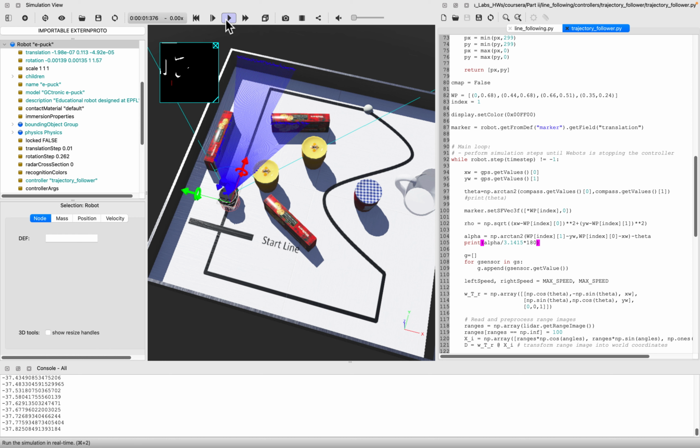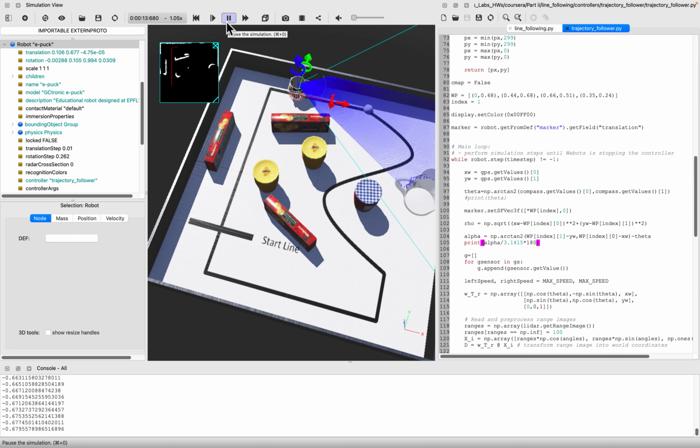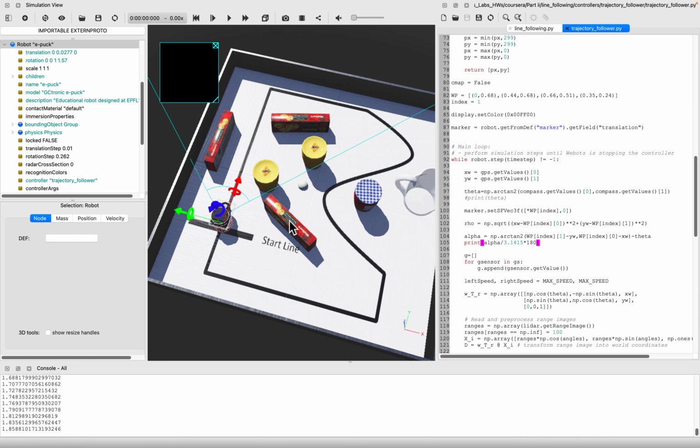Alright, so it says the robot should turn 37 degrees to the right, so minus 37, and as it goes closer this angle is increasing as the robot has to turn harder, and at the end we expect the robot to have to turn 90 degrees. Now when I keep turning, because I'm actually now turning due to the line following, I do turn in the right direction, the angle gets smaller, and now the error in angular direction is close to 0. So this looks quite promising.